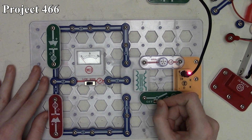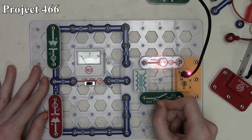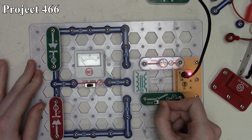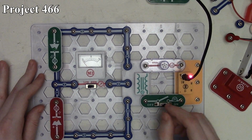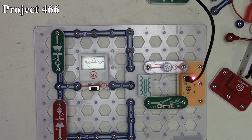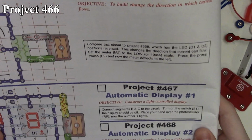And by turning the switch on and off really quick, we can make both LEDs turn on and off because we're creating an alternating current or AC signal. And as we're doing this, we can see that the meter is only deflecting below 0 because, again, the current is going in the reverse direction of what the meter expects. So because of that, it deflects to the left. So that is how Project number 466 works. Now we're going to move on to Projects 467 and 468, which is the automatic display.